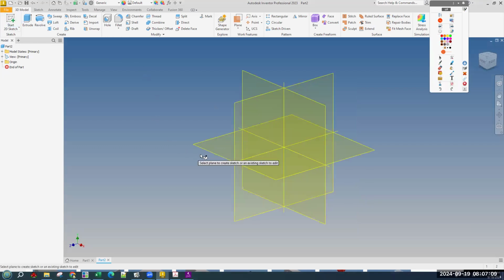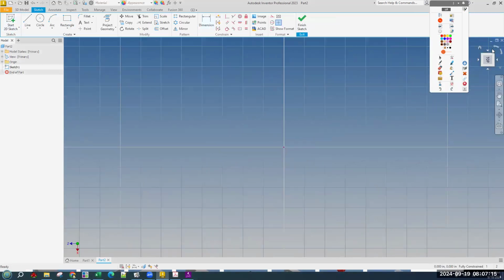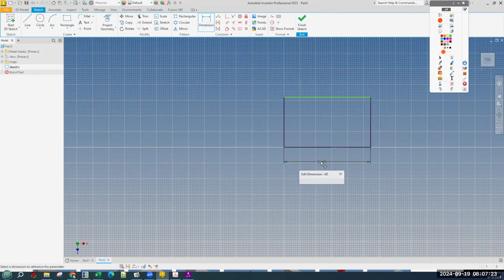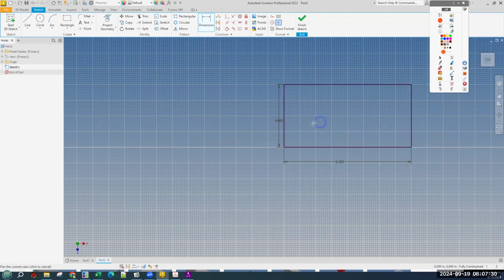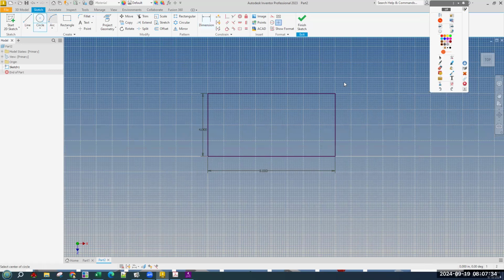Let's do a sketch. And again, we can start on the ground, which is XZ. And I don't know why it guesses to rotated, but either way, I'm just going to make a rectangle there, start it, snap to origin just because, make it 8 wide, 4 tall. Well, again, technically that's 4 deep. It's depth.